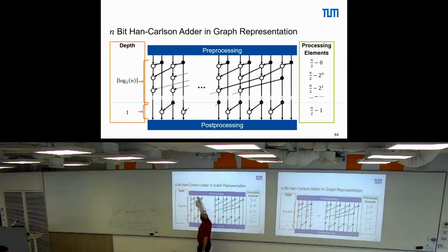We take just this input. Maybe I take one where I can somehow take the index. So let's say 0, 1, 2, 3, 4, 5, 6. So this is G6, P6. So we combine here G6, P6 with this path. And this path is on the very left. We have from here G0, P0 combined with G1, P1.